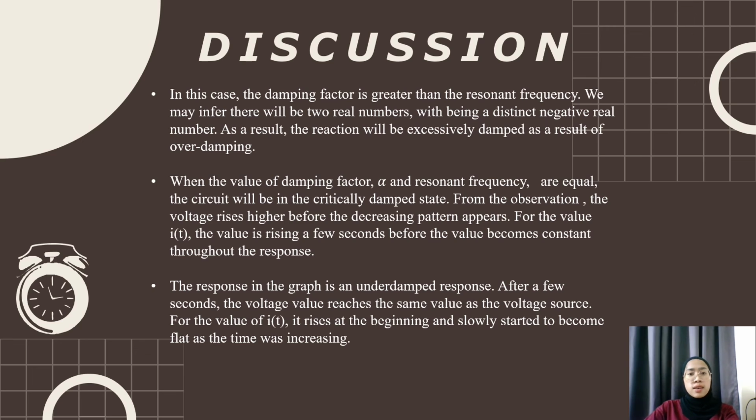Discussion. In this case, the damping factor is greater than the resonant frequency. We may infer there will be two distinct negative real roots. As a result, the response will be overdamped. When the damping factor and resonant frequency are equal, the circuit will be critically damped.